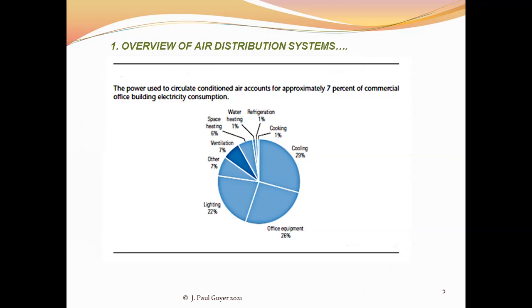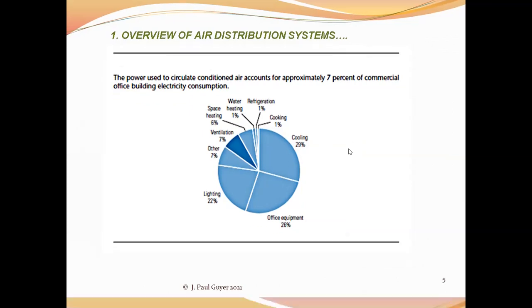energy savings. And so right sizing the fan system, or better matching the fan capacity to the requirements of the load, is an excellent way to save energy in air distribution systems. So is the fan oversized in your building? If you can replace that fan with one with a lower power requirement, you save some energy. So that's a general concept to